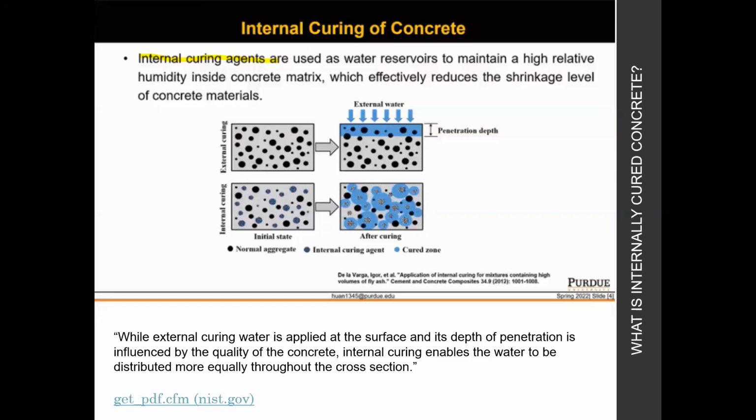But what this is going to mean through more evenly curing a concrete system is less volume change. So less curling, less cracking, less efflorescence. And if you're removing cement, less sort of negative reactions from the concrete mix itself.